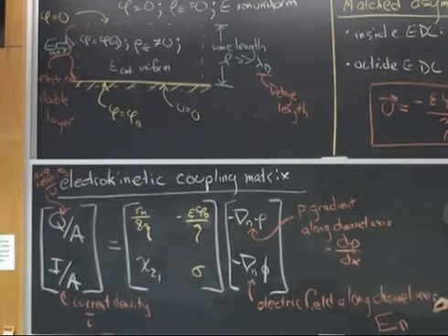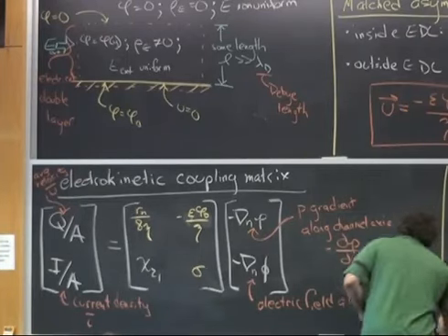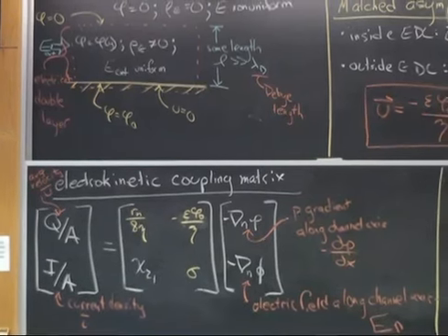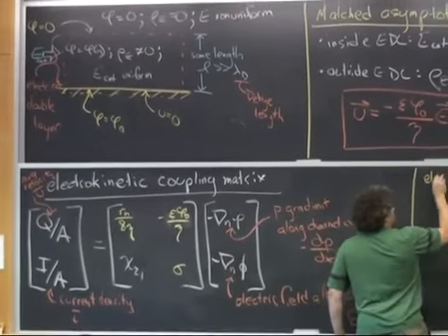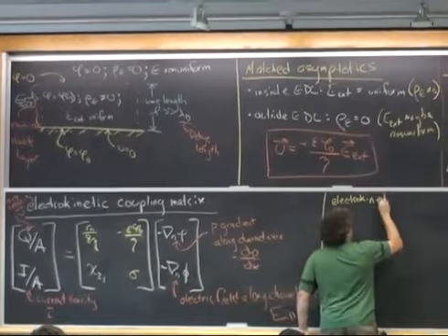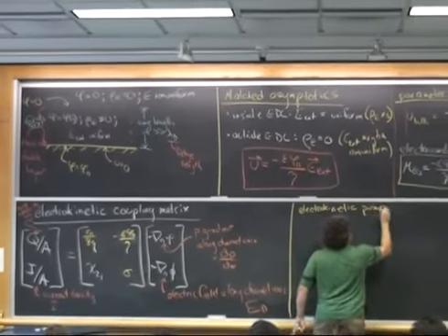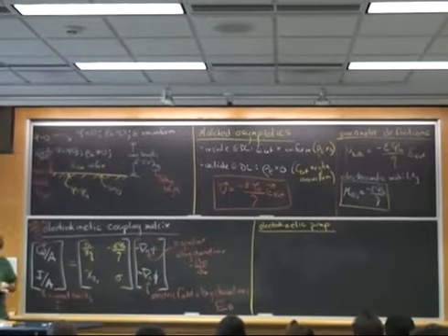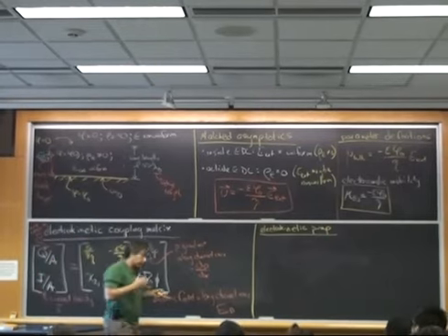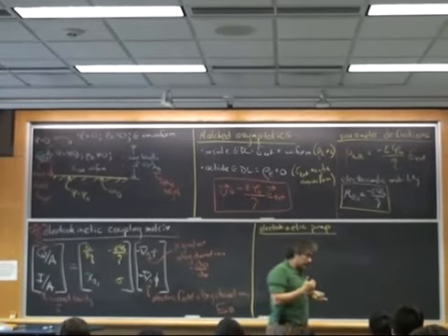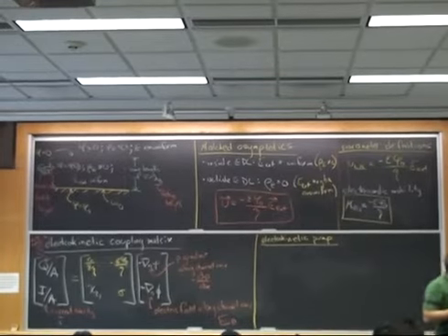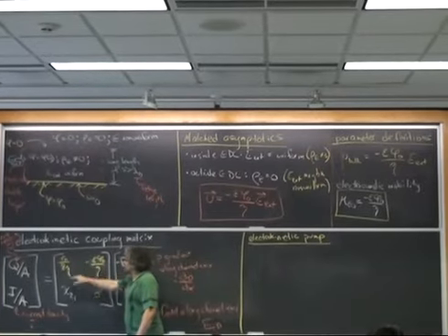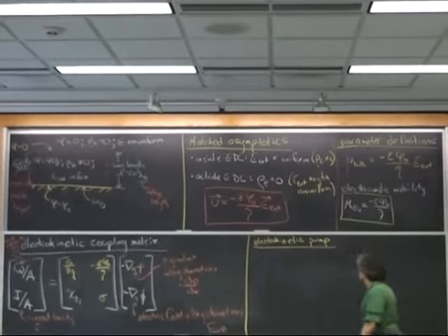And so I want to start by talking about a straightforward application of electroosmosis that's particularly relevant to microfluidic devices, and that's called an electrokinetic pump. It's perhaps the most basic example of the Couette flow, the surface-driven flow, combining together with the pressure-driven flow, the Poiseuille flow, in a specific context that highlights what the differences in scale do, and what simultaneously highlights how, once we take these terms and put them into this electrokinetic coupling matrix, a bunch of stuff gets a lot easier.